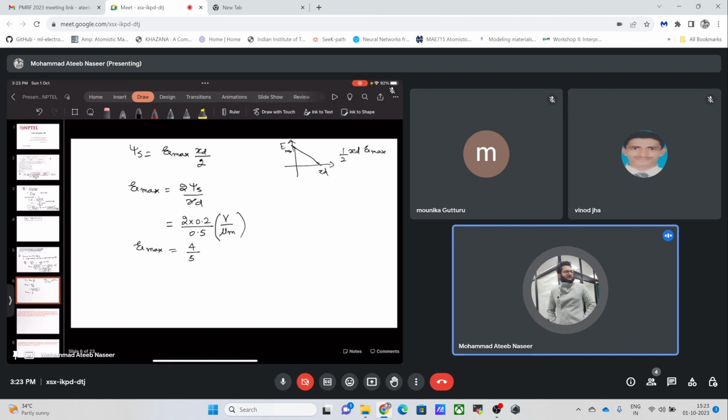Now at the boundaries, when we are at this interface, this displacement relation has to be true. Epsilon s times the electric field in the semiconductor has to be equal to epsilon ox times the electric field in the oxide.